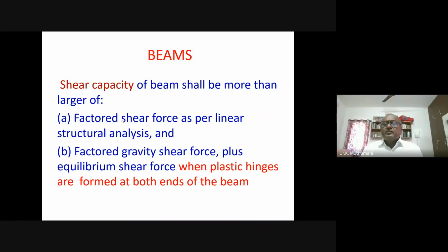The next topic I want to come to is, okay, bending moment you are taking care of. The only thing is the provision of reinforcement; actually 13920 governs more than your idea of getting the steel based on the bending moment that comes. The interesting point as far as the beams are concerned is the shear capacity. It is the most important thing that can happen. I want you to know this, it is a very important thing.